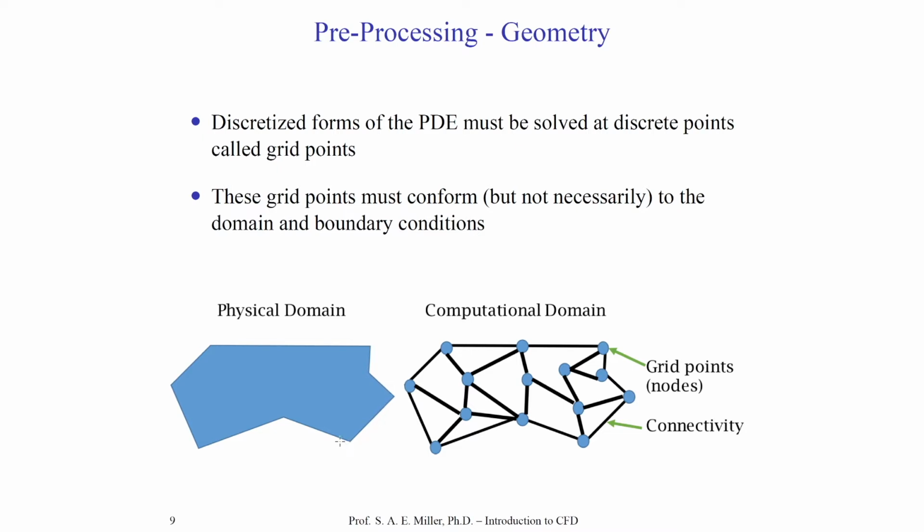For example, these might be a wall with a no slip condition, and this might be another wall with a slip condition. This could be where the flow enters the domain and where the flow exits the domain. The solution might look like, hey, there's some velocity vector or streamline coming through the domain from left to right. We can also set boundary conditions in a different way.